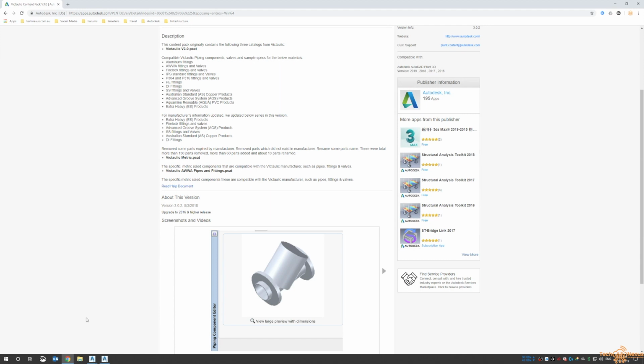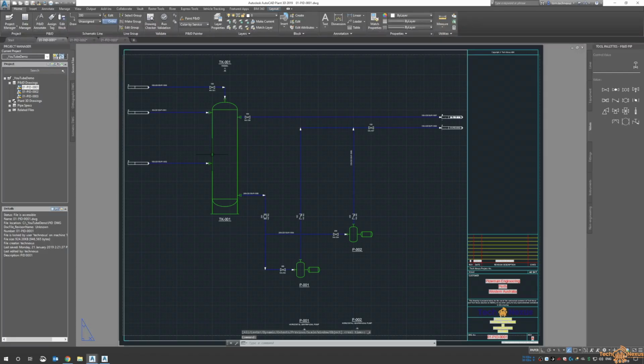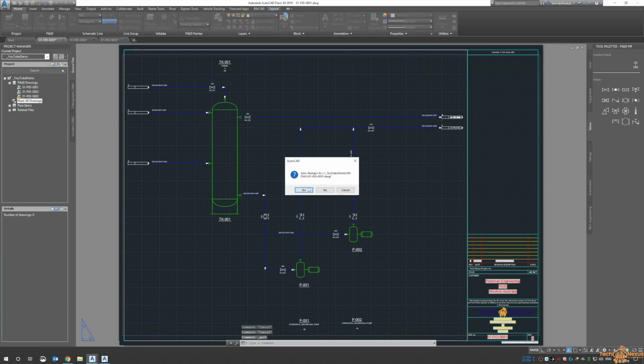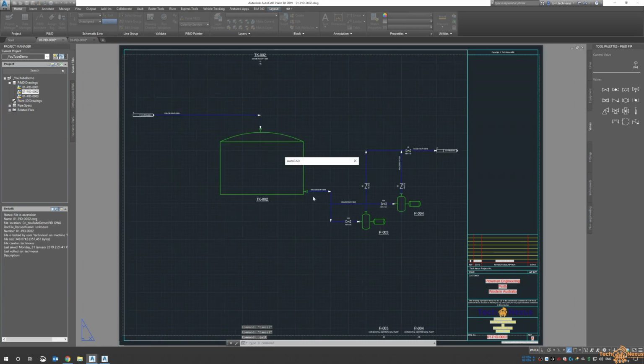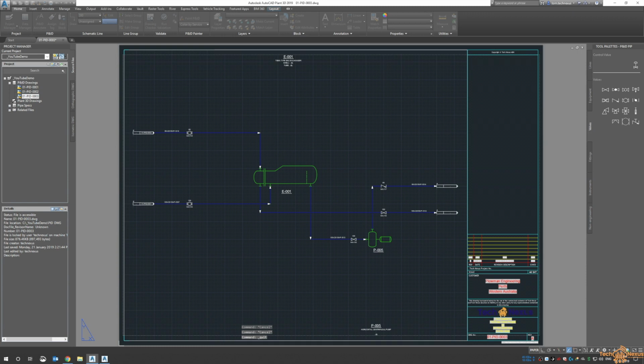your Plant library. So if we're looking at our P&IDs, I'm just going to shut this down because we can't go from the piping of a P&ID into the 3D side without at least knowing which spec we're going to use, and for which service, for whichever temperature rating, pressure, all that kind of stuff. So we're just going to shut down the P&ID because we don't need them just yet.